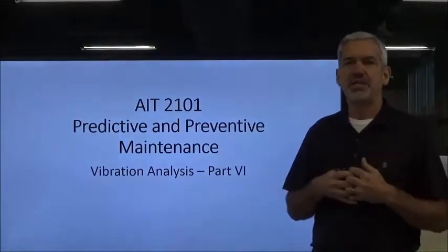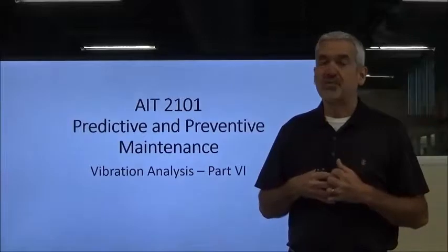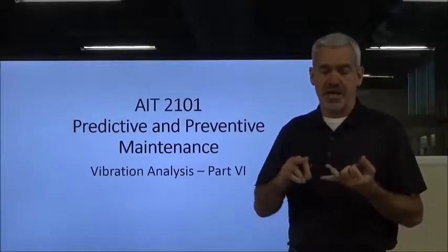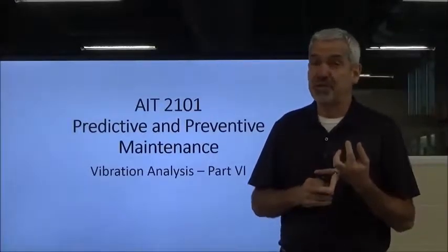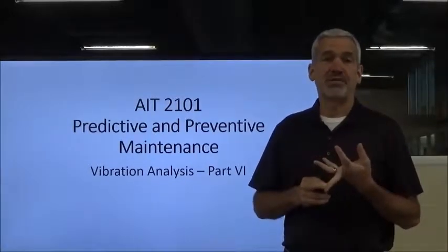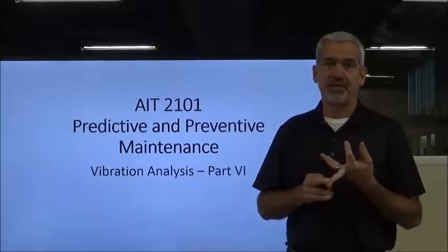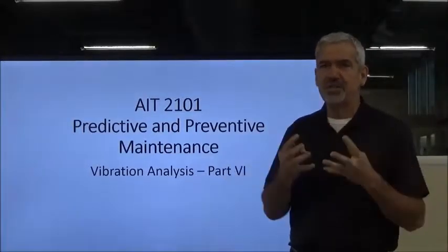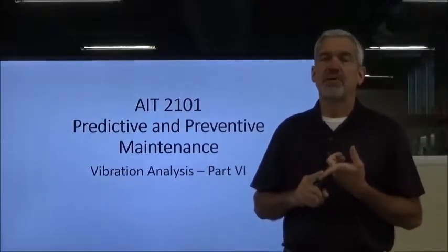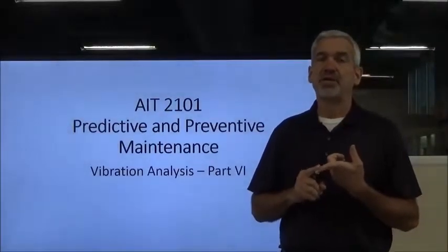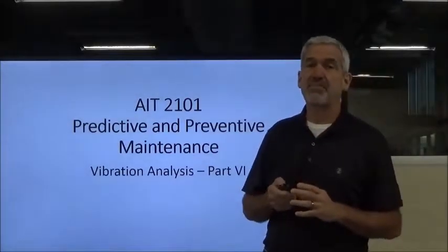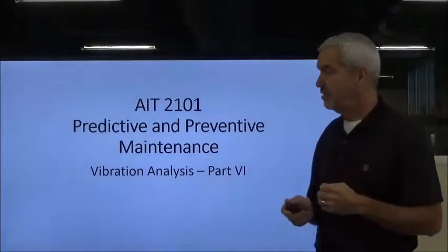And it gives you an opportunity to plan and schedule the maintenance, which is far more economical than reactionary maintenance, where you oftentimes have to have overtime. You're down unexpectedly. You have to explain that to your customers who are waiting on products that are supposed to be coming out of these machines that are now down for the count. Oftentimes you have to fly components in, and freight, your hotshot freight, is very expensive. So all these things roll in together. And also, whenever you work overtime, studies show that most industrial accidents happen during overtime hours. So all these things roll in together, and vibration analysis can help eliminate a lot of the excessive costs.